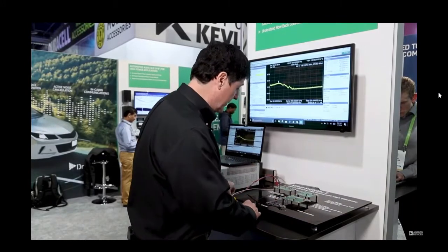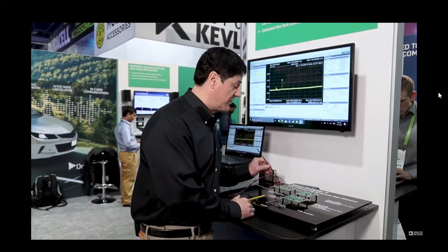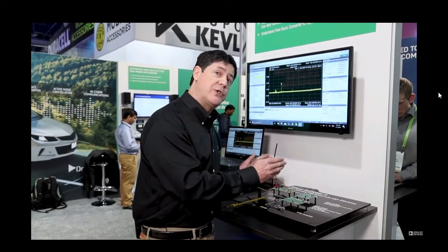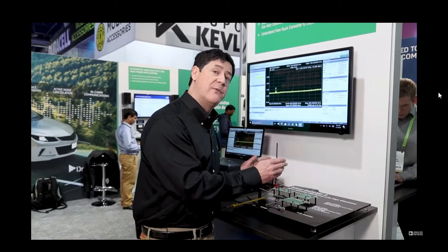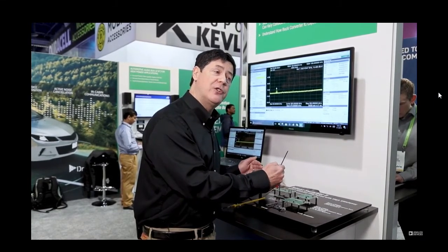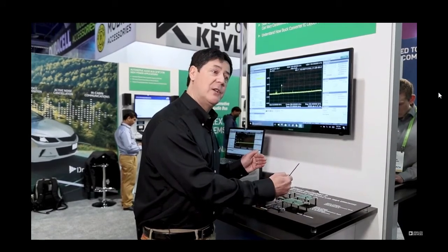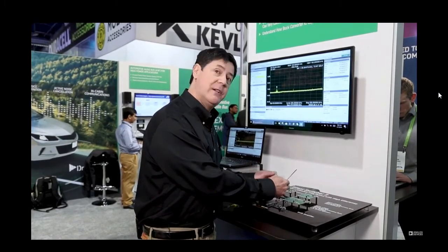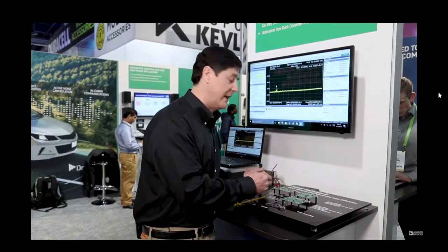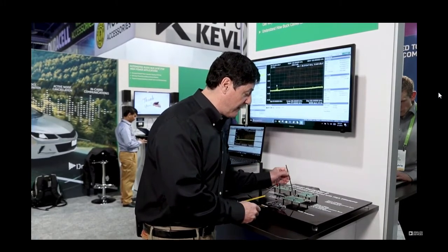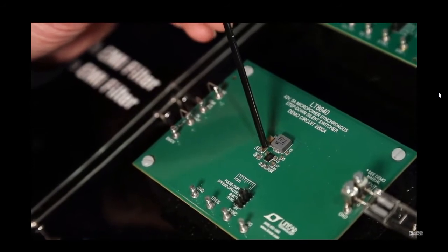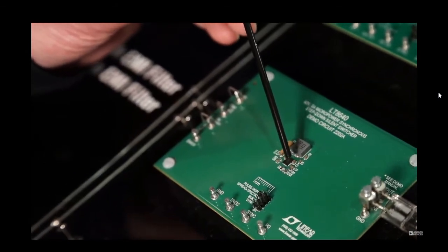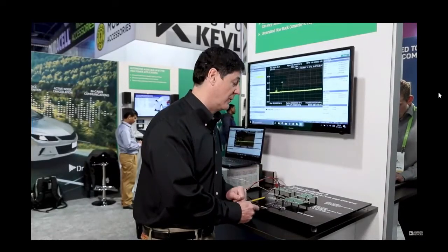On this device, what we have done to lower those emissions is basically take the switching regulator and break it into two halves so that we can have the magnetic cancellation from opposite sides, which significantly reduces the EMI emissions. So we do that inside the chip and tie the output together so that we get a single device. It is very important to have the filter cap between the respective V-in and grounds on each side of this chip as close as possible to minimize those emissions.